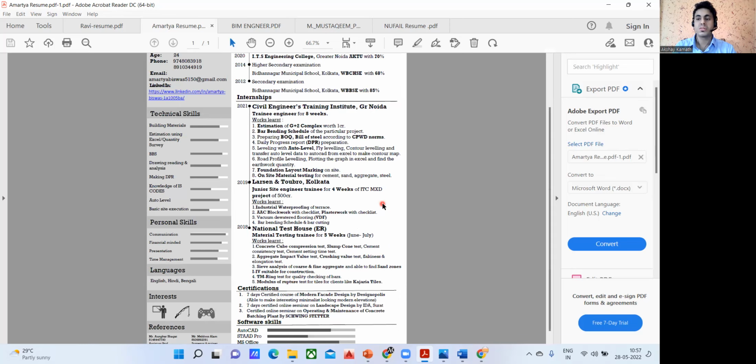I've already explained all those things in my course. Can you not explain that? The standard size is 200 mm by 100 mm by 100 mm. Then based on that, he may ask you, if I give you 1 cubic meter, how many blocks are there? Can you find it? 1 divided by the volume of my block will give me the number. Simple. So you are inviting him.